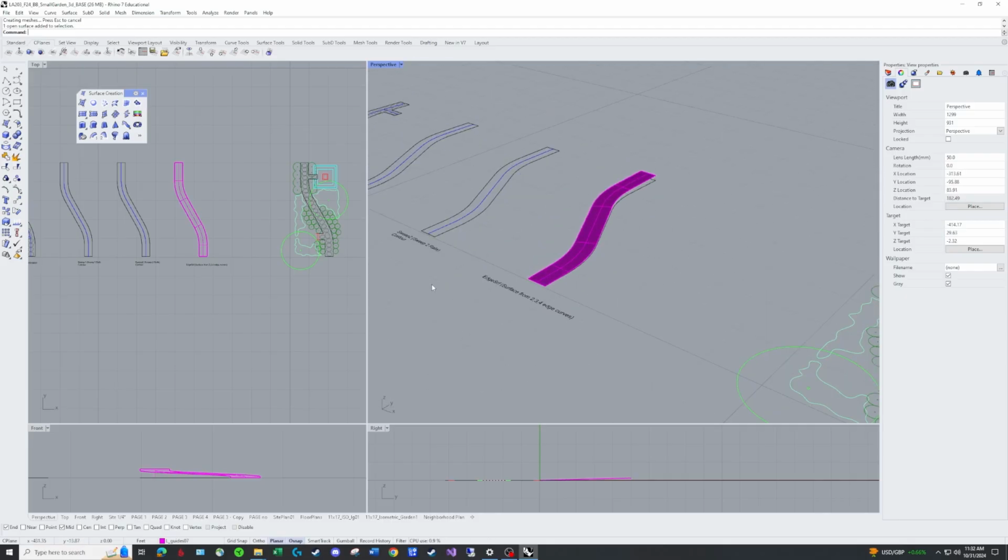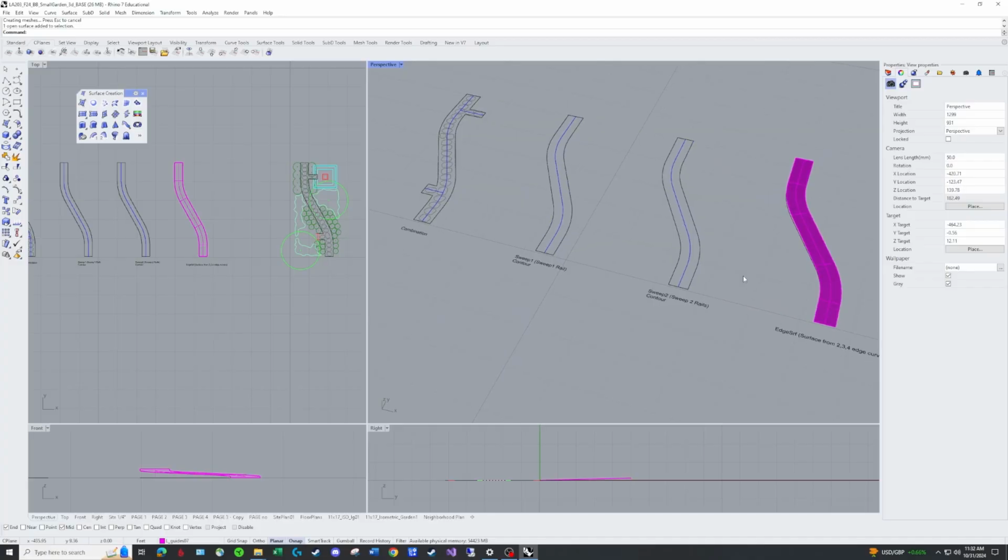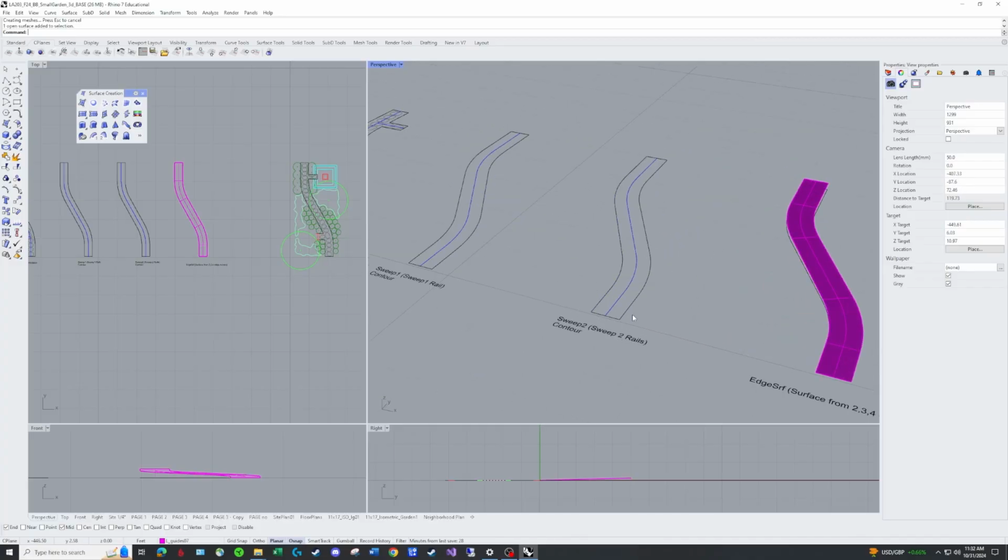Again, I do think this works for this problem. There are other ways that I think are better, especially for more advanced pathway systems, and so that's what we're going to do now. And here we'll use the command sweep to rails, and then we'll also take a look at the contour command, which for the sweeps is important that you see what's actually happening with the contour command.